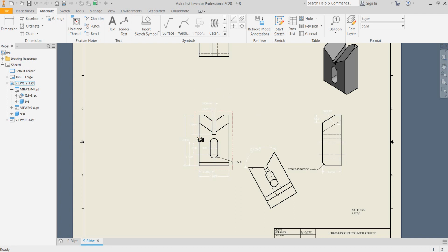Okay, so you remember back earlier where we were talking about true size and true shape in planes. This line and this line are true size in the front view because we're looking at them and they're parallel to our viewing plane. So those are true size. But the shape is not true shape, and we have to make an auxiliary view and then another auxiliary view and then another one to get around to that. We got a whole bunch of views in here.